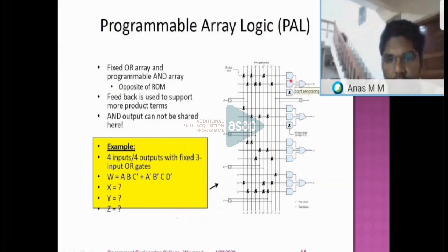This is a circuit of programmable array logic. We are using fuses to connect various inputs to the AND gates. From there, we are fixedly connected to the OR gate. From there, we will get the output functions or Boolean expressions. So let us analyze the first expression.